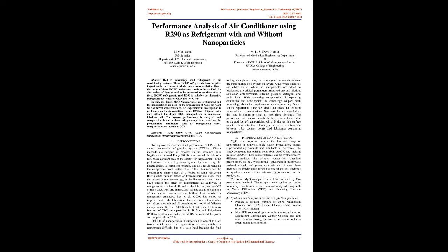These HCFC refrigerants have negative impact on the environment which causes ozone depletion. Hence the usage of these HCFC refrigerants needs to be avoided. An alternative refrigerant needs to be evaluated as an alternative to these HCFC refrigerants, and R290 is suitable as alternative refrigerant due to its low ODP and low GWP.